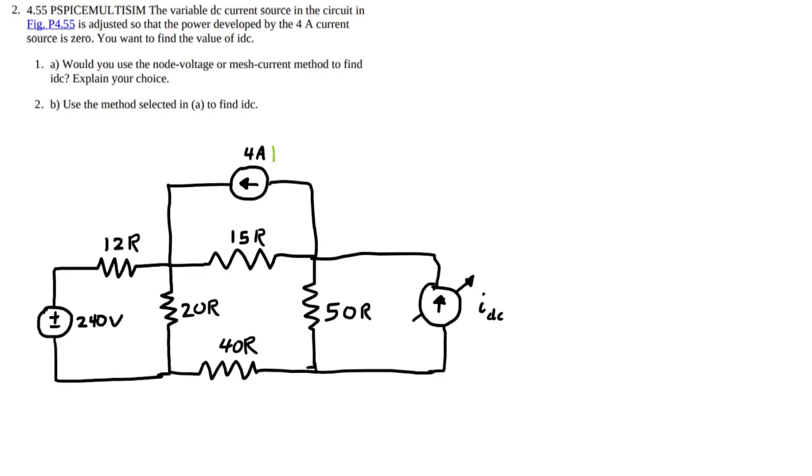So since we can't make this go down, then we have to make the voltage across it, say Vs, equal to 0, which means that V1 equals V2 over here, which also implies no current flows to this resistor, which will become important later. So I'm going to label these nodes real quickly.